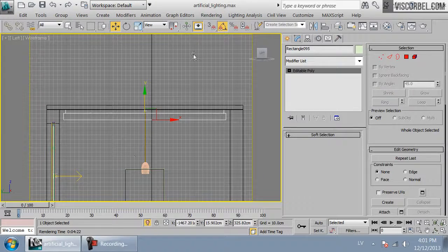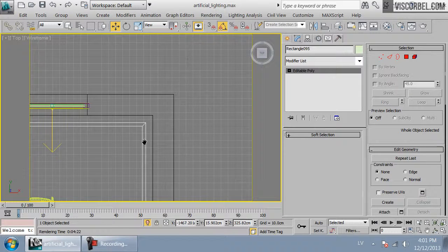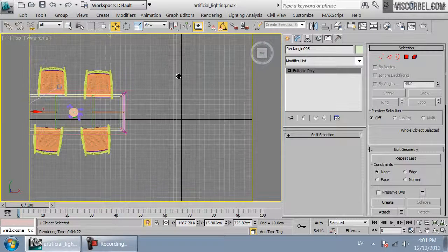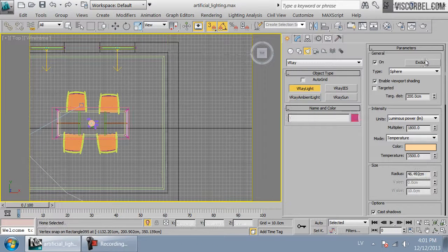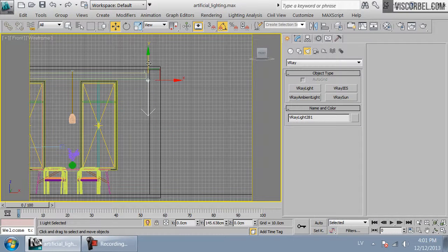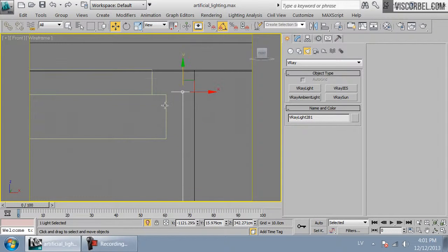And many people that have not seen these lights in real life or do not know how they are constructed in real life usually use a technique like this, where they create a light, point it directly downwards. Okay, so plain light, point it downwards and expect it to look good. That's really not how it works. You do not put the lights in this direction, since if you can see them in render, it looks weird. They are too bright, or they are too aliased, or the light distribution looks weird.